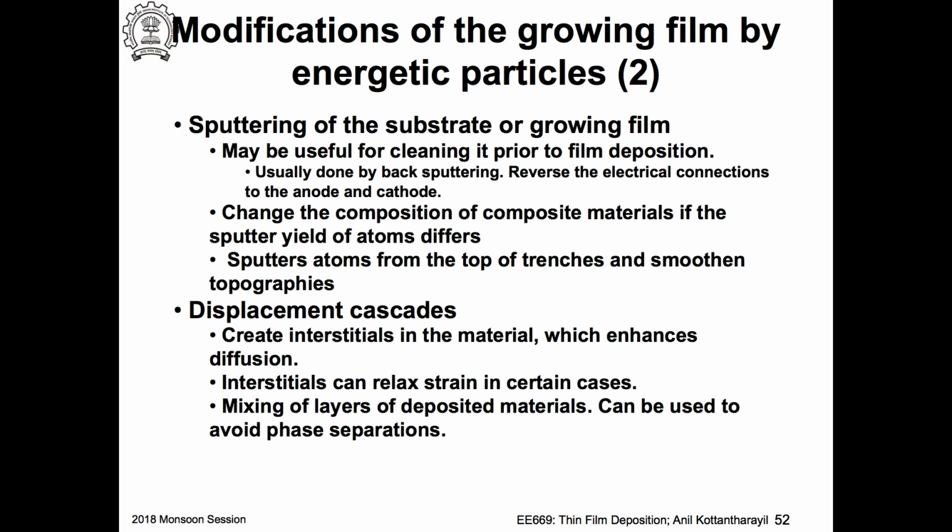But with oxygen plasma, you have to be careful in a sputtering system, because if you let in oxygen, the surface of the target, suppose it is aluminum, can become the oxide of aluminum. Then if it is a DC sputtering system, you have a problem, because that will get charged and so on. And the initial films that you deposit will be aluminum oxide. But I'm just mentioning that in plasmas, these possibilities do exist.